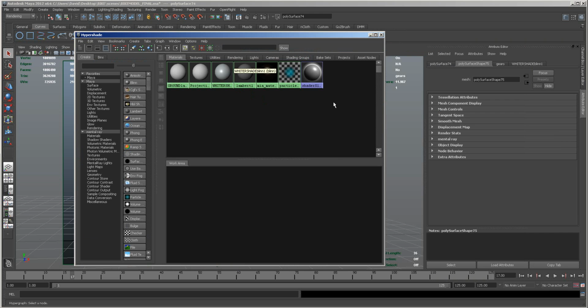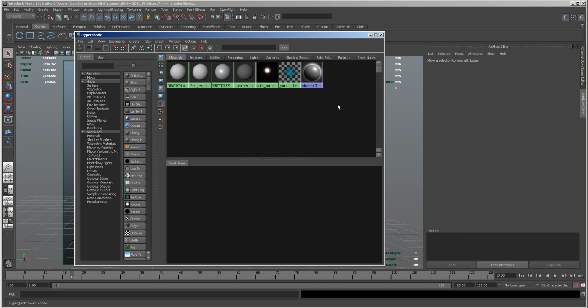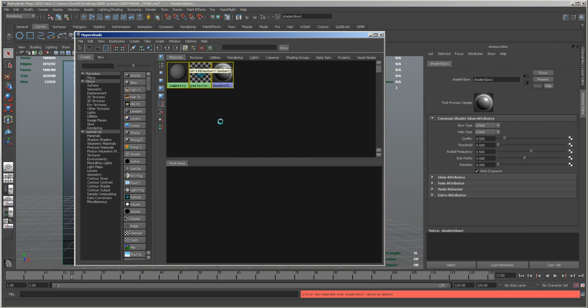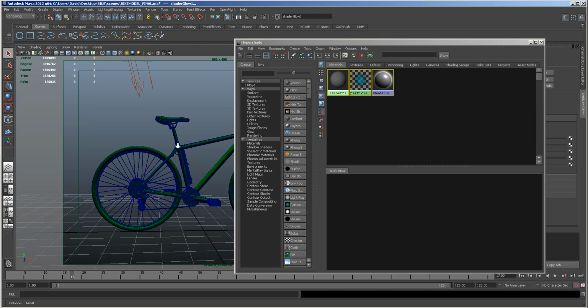Okay, so the first thing I need to do is just get rid of all of these materials, because we're going to be applying new ones. I've just selected across them, and then I just hit delete. It will basically clear all the materials, and these are turned to a kind of greeny colour, and it means that there's no material assigned to it.